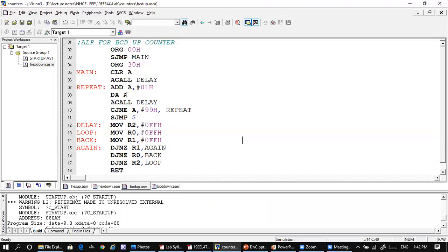That's why the DAA is used here. After that, again, the subroutine is called. Now the counting will start from 0 and go up to 9, because that's a valid BCD number. It's a packed BCD, we can say. So now let us execute this and see this program.